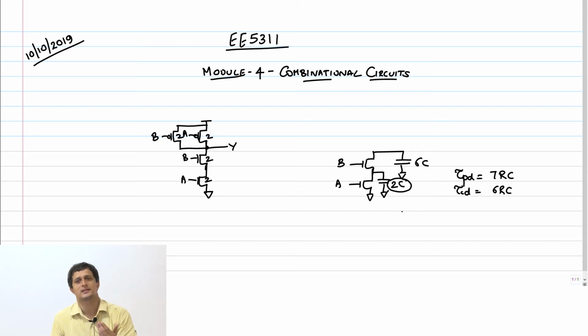So clearly there is a difference in these two inputs, right? And therefore, when you have a critical input, when I say critical input, I mean a timing critical input, then that input has to be connected to the transistor which is closest to the output. Okay. So for example, these two signals A and B, right? A might actually switch early, but B might switch later.